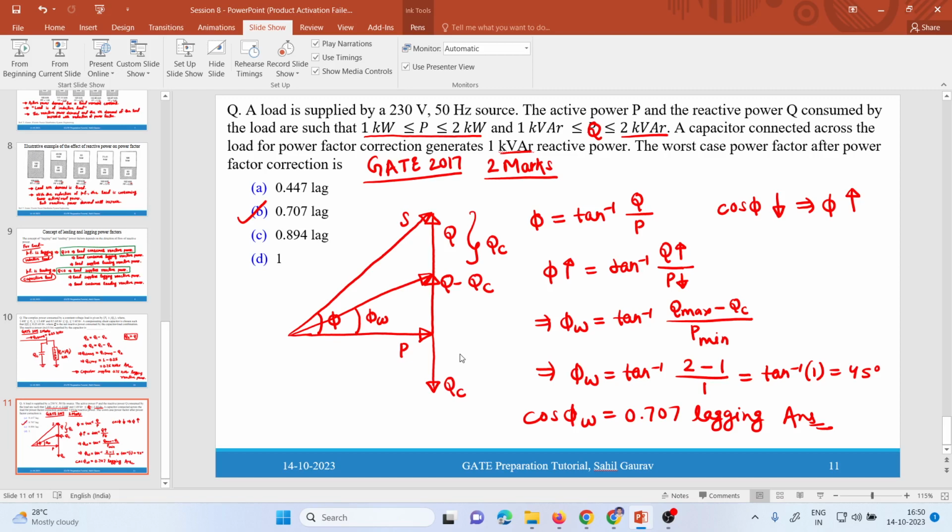Yes, sir. So for supercapacitors, if you supply power in a transient condition, then generally we use the supercapacitor. And capacitors and batteries are energy storage devices that we use for the steady state period. But for improving the profile under sudden power demand, we use the supercapacitor. So we don't consider the transient here. These are steady state conditions only.